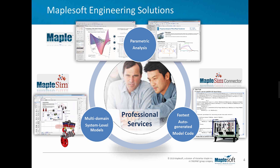So MapleSim sits on top of Maple and uses the technology of symbolic computation of Maple. The same symbolic technology enables MapleSim to generate code from the models that get created with graphical means, the block diagram of different blocks, and from those components, equations are generated. Those equations are manipulated with symbolic technology, and then C code is generated from that.